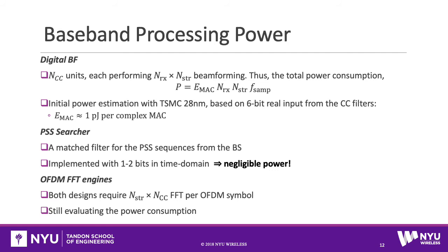Since the total sample rate across all of the component carriers is f_samp, our initial power estimation, again using the Spiral tool based on the 6-bit real input from the component carrier filters, is around 1 picojoule per complex MAC operation.